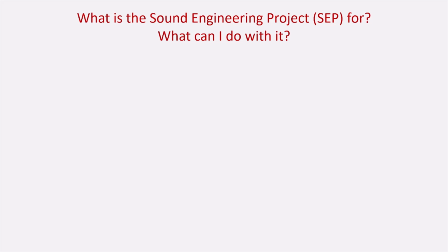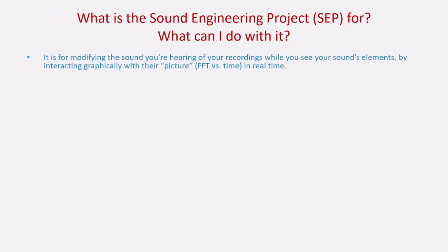So what is the Sound Engineering Project? We're going to call it SEP from here on. What is it for, and what can I do with it? It's for modifying the sound you're hearing of your recordings. You can have any recording of anything, 2 channels, and with or without tachometers, and you see the sound's elements by interacting graphically with an FFT versus time, of which you can control the balance of time and frequency resolutions, and then you can do all sorts of interactive things by drawing and immediately seeing the result and hearing the